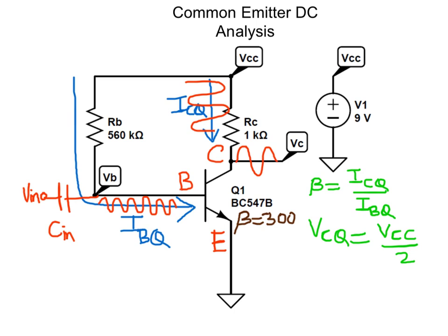For this circuit to function as an amplifier, we have to ensure that the base emitter junction is forward biased and the base collector junction is reverse biased. So VBE, or the voltage across the base emitter junction, should be greater than 0, and VBC, the voltage across the base collector junction, should be less than 0. If we satisfy this condition, then we will ensure that the transistor Q1 is biased in the forward active region. This is a prerequisite for the circuit to function as an amplifier.